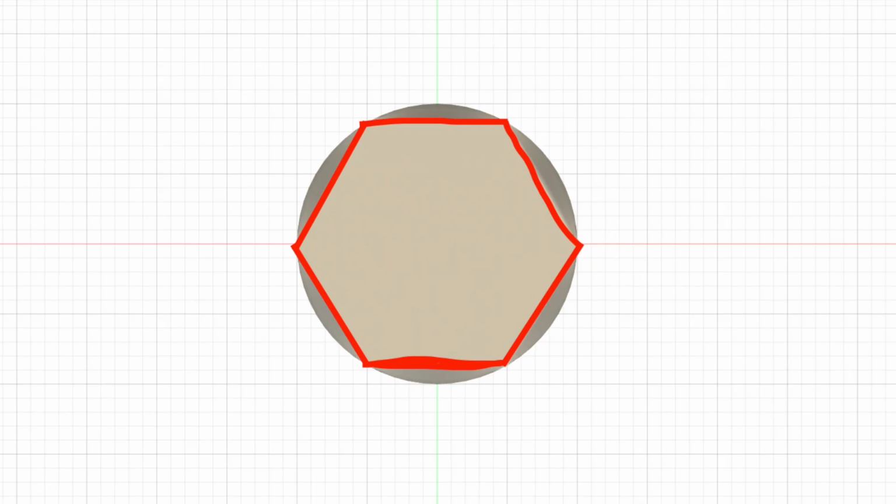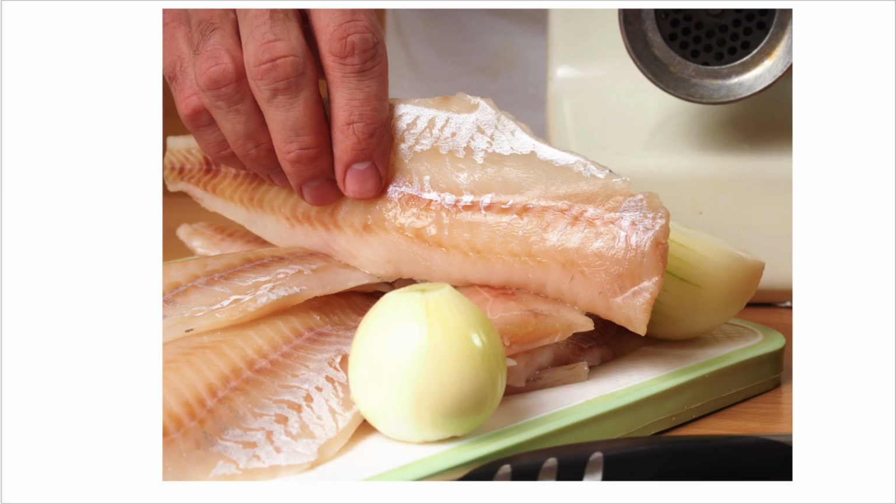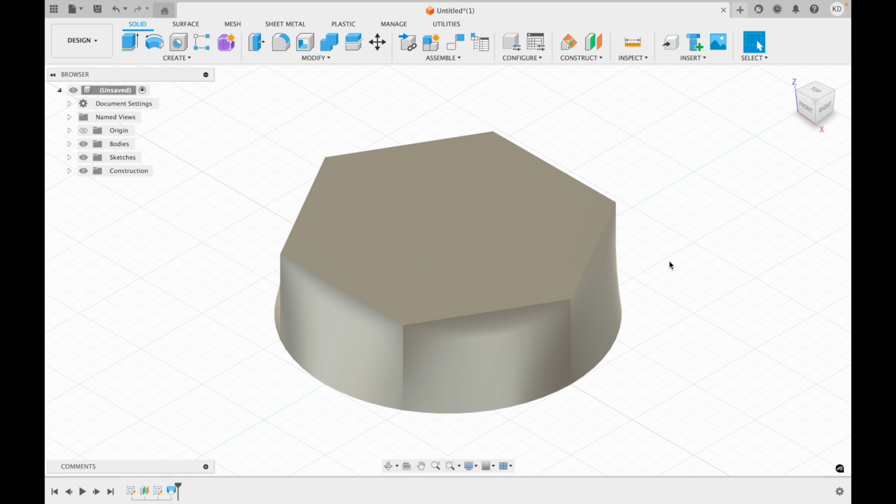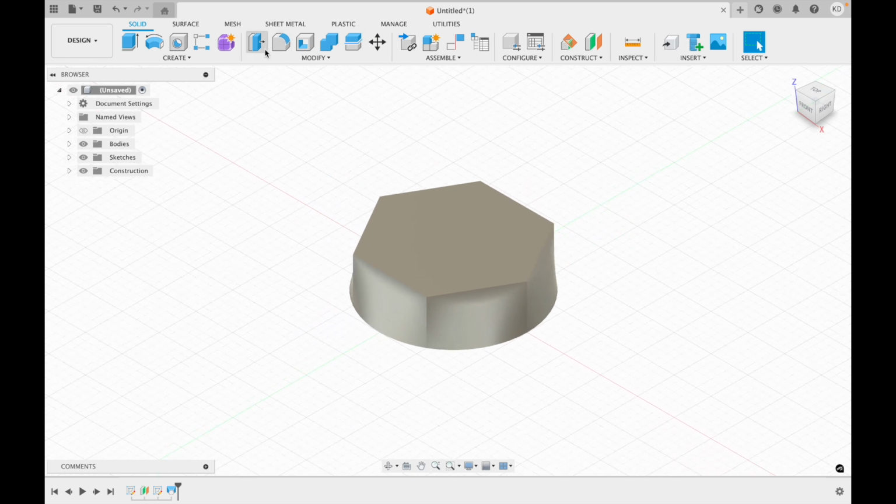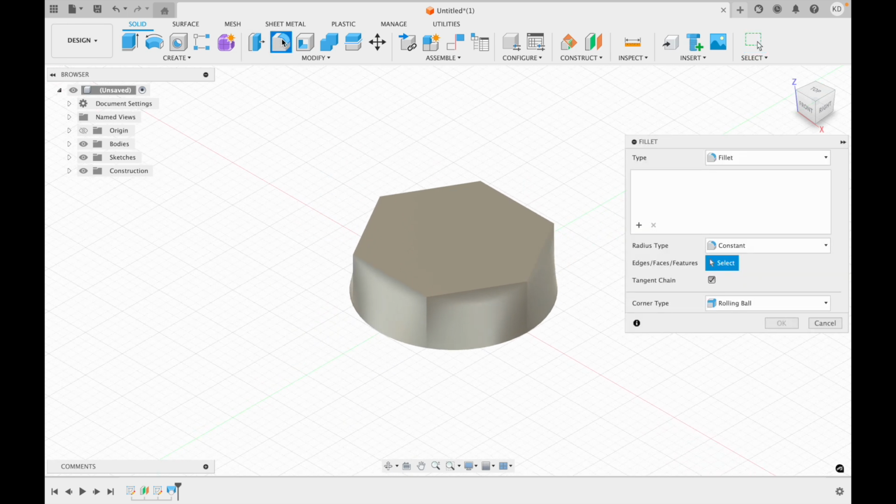So this solid right here has way too many sharp edges and sides, but what we can do to smooth that all out is fillet it. And despite this being the spelling of the word, it's pronounced fillet, not fillet, because you're not filleting a fish, which annoys me. So now I'm going to fillet these edges, and essentially when you fillet an edge, you are making it smoother by taking these sharp edges and making them rounder.